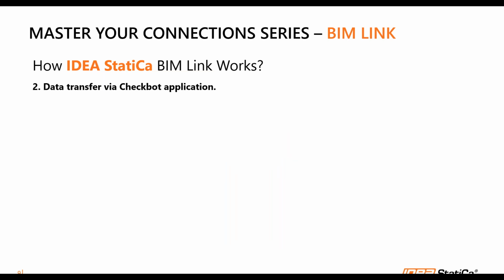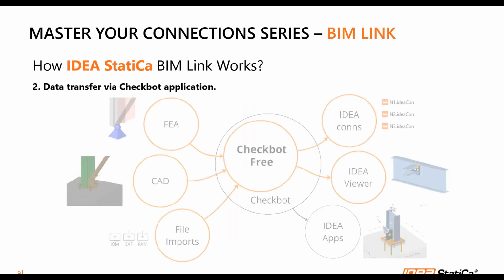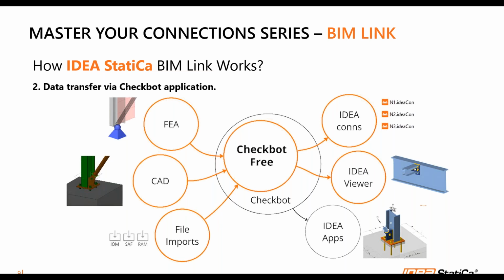Data transfer from FEA projects to IDEA StatiCa is managed through the Checkbot application. Checkbot is an application used to import and manage structural joints, connections, and members that you want to analyze and code check in IDEA StatiCa. Checkbot also allows synchronization of imported models after you update your source FEA or CAD projects.